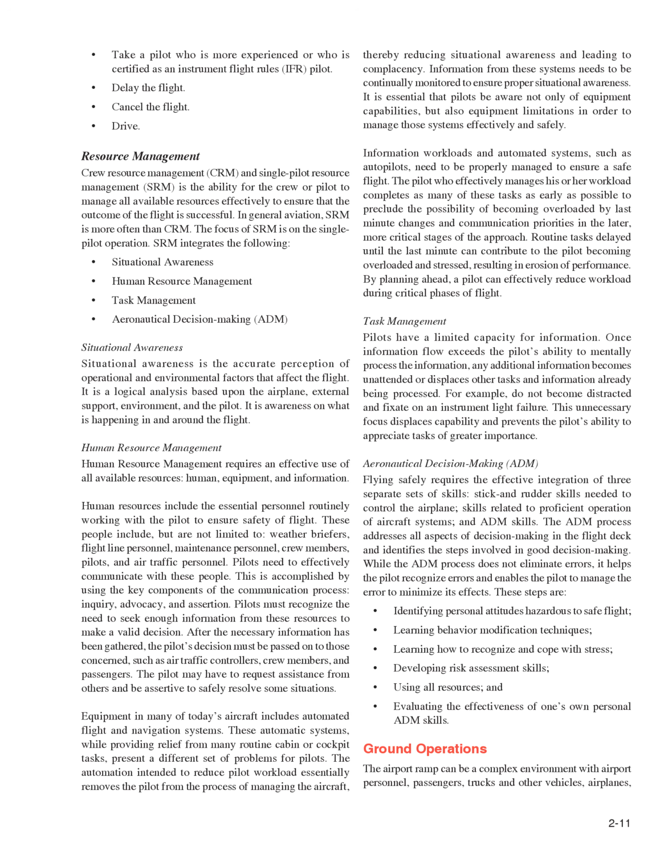Drive. Resource management. Crew resource management, CRM, and single pilot resource management, SRM, is the ability for the crew or pilot to manage all available resources effectively to ensure that the outcome of the flight is successful. In general aviation, SRM is more often used than CRM. The focus of SRM is on the single pilot operation. SRM integrates the following: situational awareness, human resource management, task management, and aeronautical decision-making, ADM.